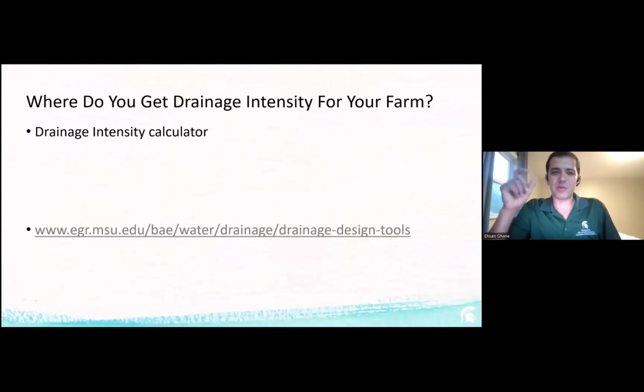So 10% plus or minus. If you're lower than that, then you need to make a phone call to do more investigation about that. And if your drainage coefficient is higher than drainage intensity, you're in good shape. You are not restricting that. But there are cases that I have seen where this has happened, and there are fields out there where this is happening.